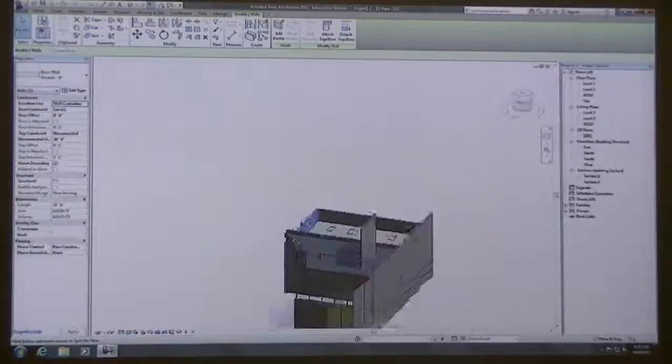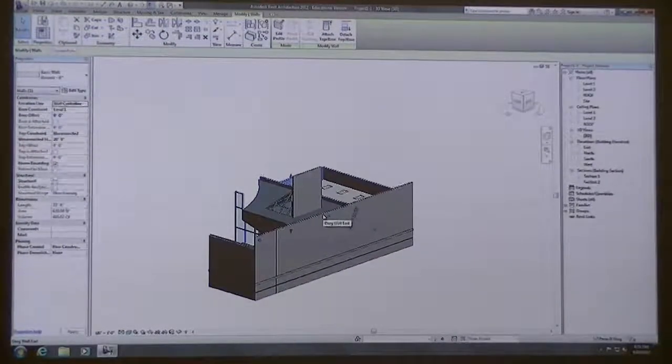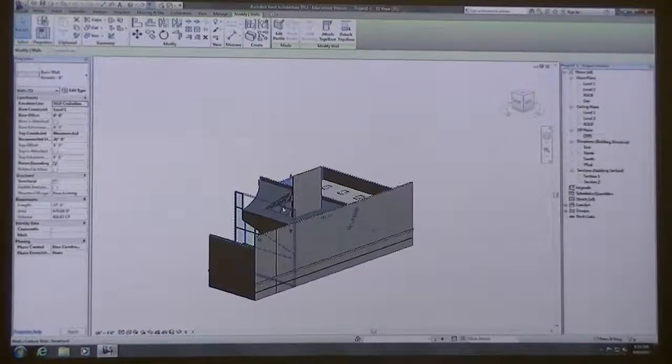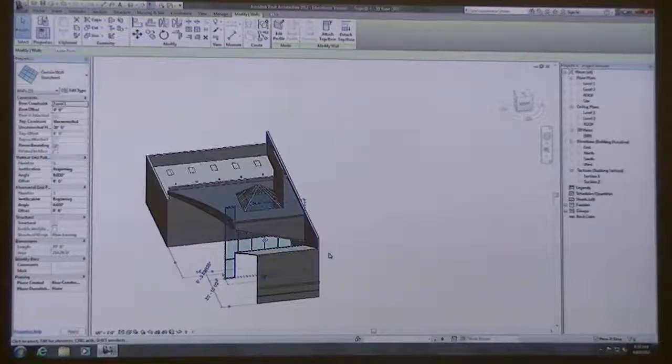And if you've got walls that are 80 feet long or so on, if you don't have any kind of articulation to it, it kind of looks like you haven't been really thinking about what type of material that wall is going to be and how large of a panel you can actually get from time to time. Same thing with glass, you wouldn't have an 80-foot long piece of glass, and that's why we went over adding in mullions and all that type of stuff, because you're only going to have glass that can come so large.